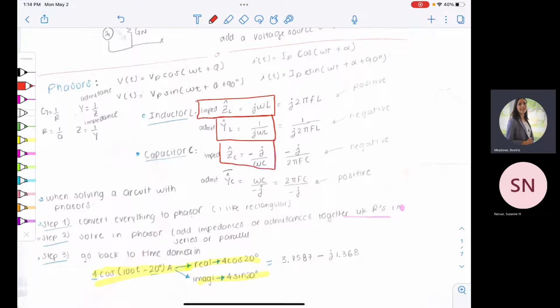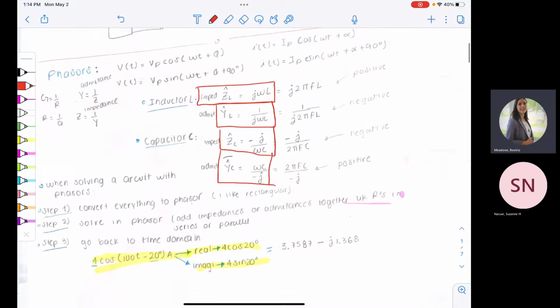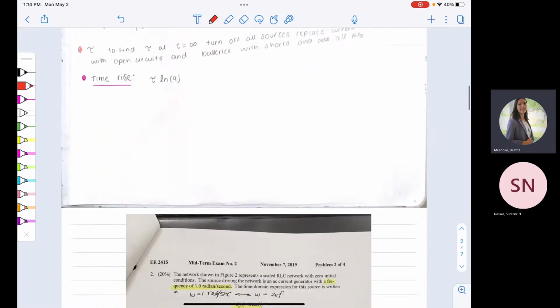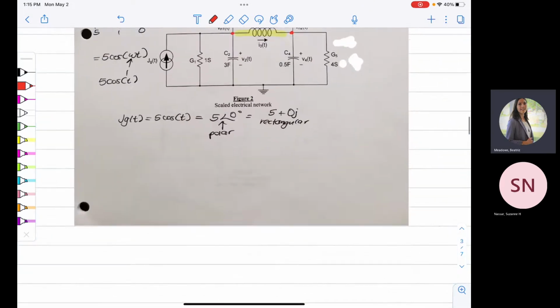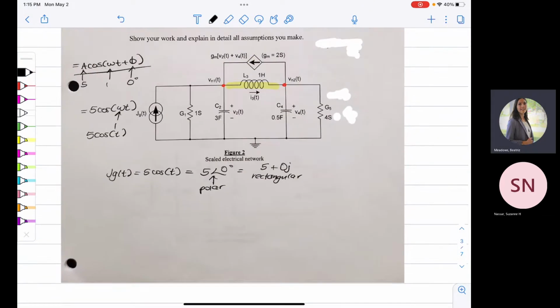But you had the negative j kind of flipped. It will be negative when you put it in your calculator, because 1 over j omega L ends up being negative j over omega L, since the j has to come to the top. So you're right. It's just a little trippy. Just plug it in your calculator.